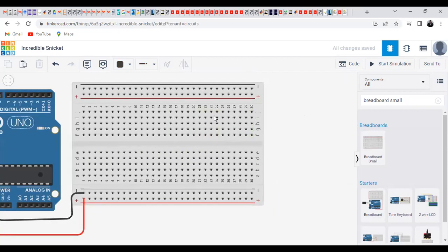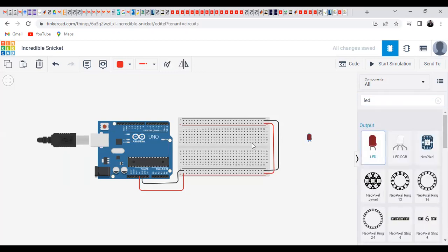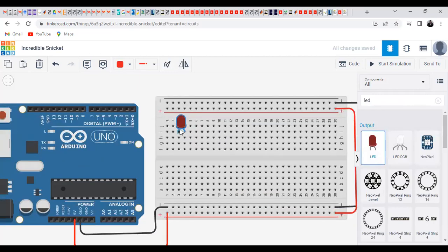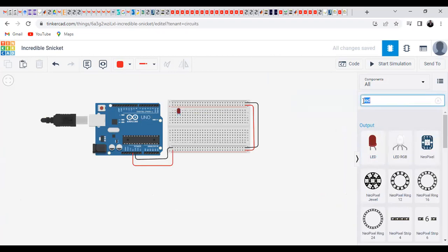In case you want to power the upper half, you can always loop from here. You can always loop from there. And then we loop the VCC, which is 5 volts DC. Then the other components we need is LED. So we search LED, pick it, we can come put it there. The other component we need is a push button.